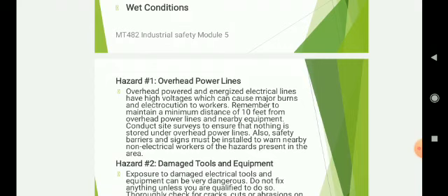Conduct site surveys to ensure that nothing is stored under the overhead power line. Nothing should be stored under the overhead power line, because these power lines may fall sometimes, and the current is still passing through, so it may cause a hazard. If some type of conductors or flammable material is stored under the overhead power lines, it may cause a serious disaster.